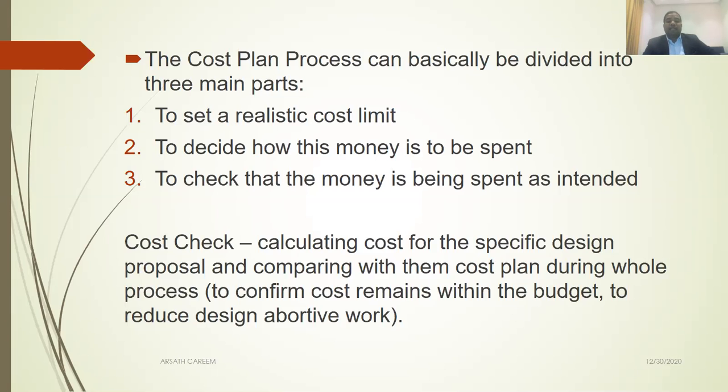Mainly, it reduces the design abortive work. After you finish the full design, if you come to know your budget is over, it's a long process. You have to come back again and start from scratch. If you do the cost check at every step of the design stage, which I discussed earlier, you will save lots of time and your design will be more efficient.